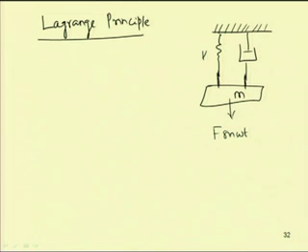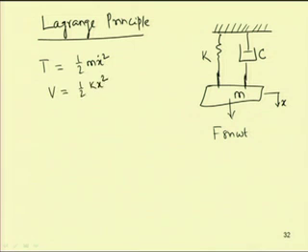It has a stiffness of K, damping C. Already we have written the expression for kinetic energy, that is equal to half m x dot square, potential energy V equal to half k x square, and also this damping or dissipation energy D equal to half C x dot square, and we have to find this expression for q k.